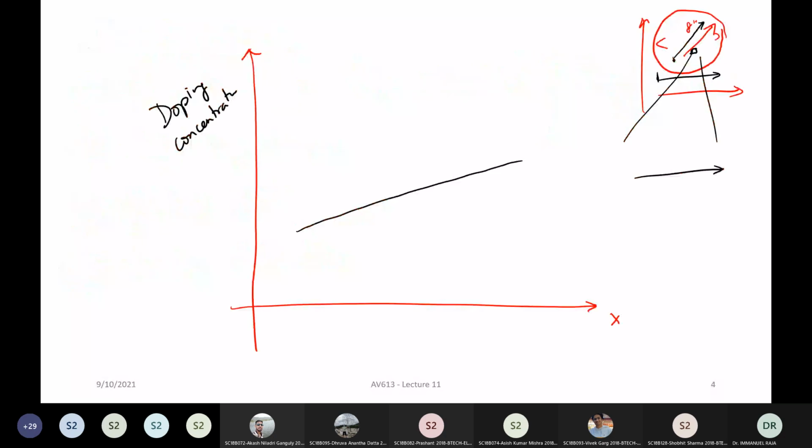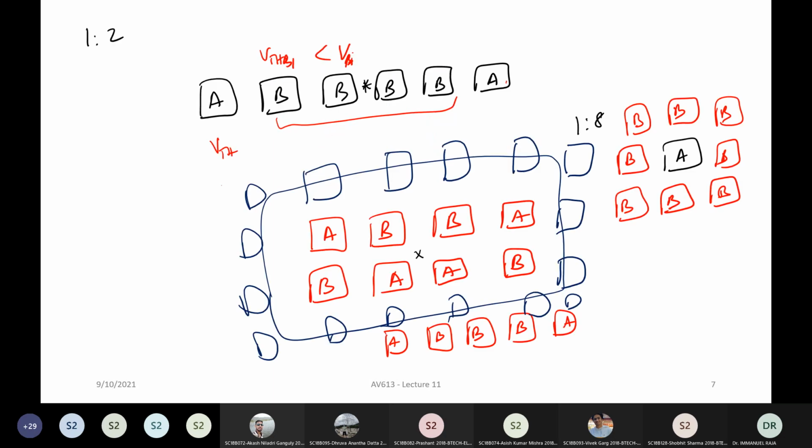Okay. Now, as the name suggests, it is random in nature. Which means that, let's say you put two transistors, let's just call them A and B for now. No matter how much effort you take, you put them close to each other, you put dummies around, you do a common centroid layout, all the effort you take, still there will be mismatch between two devices.